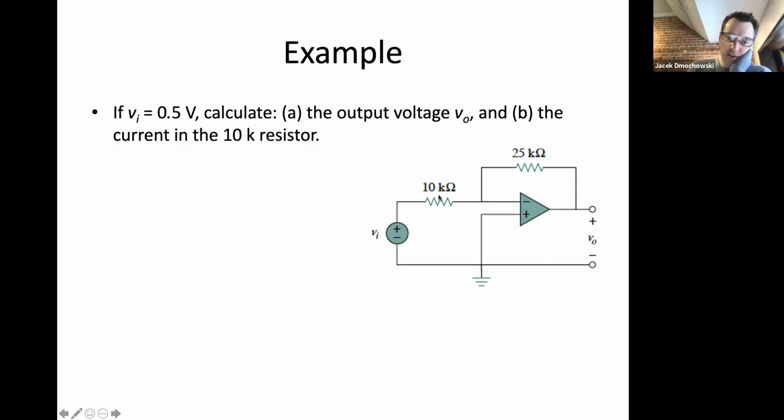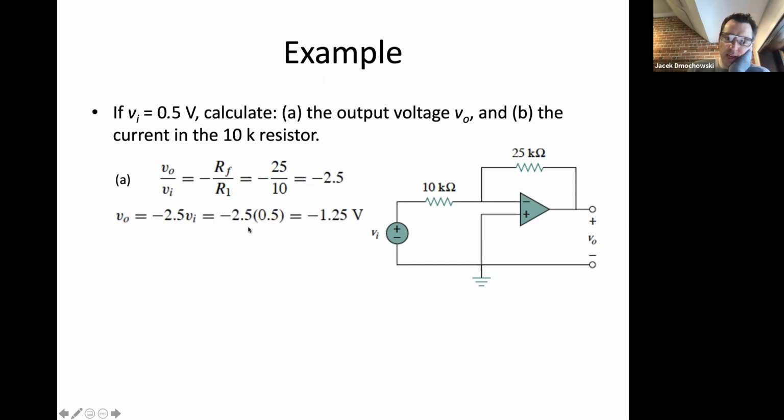Right, the gain is negative 2.5, which makes the output equal to negative 5/4 of a volt. Excellent. Right, so our gain is equal to negative 2.5 multiplied by our input of 1/2. That's 1/2 of negative 2.5, which is negative 1.25 volts at the output.